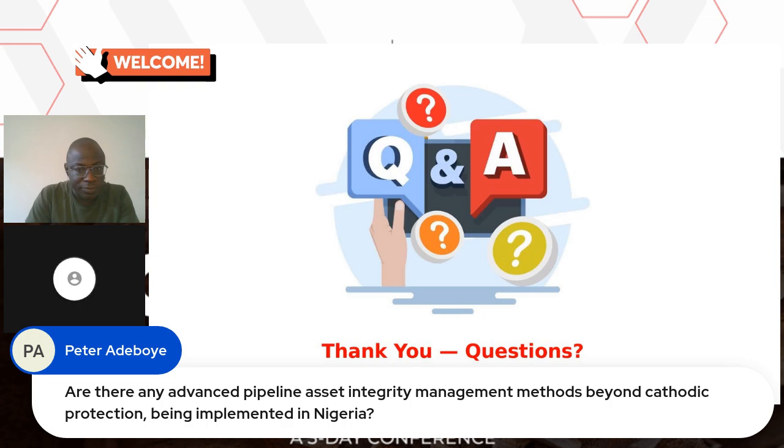Okay, yes. So it says, are there any advanced pipeline integrity management methods beyond cathodic protection being implemented in Nigeria? Well, I think generally for pipeline asset integrity management, most of the things which we need to do, we already know what we need to do, right? If we are doing inline inspection, if we are doing fitness for service assessment, if we are doing this one by NACE, which is an alternative method to inline inspection, if you are doing cathodic protection, internal corrosion chemical treatment, and the likes, we already know what to do generally.